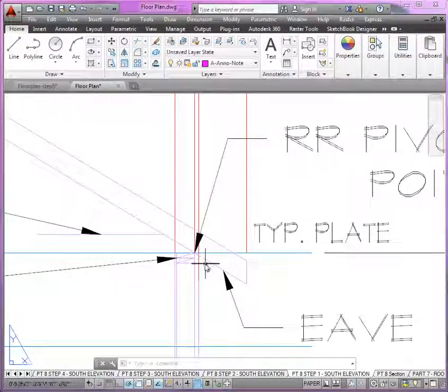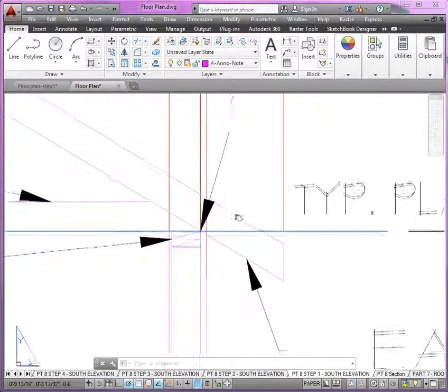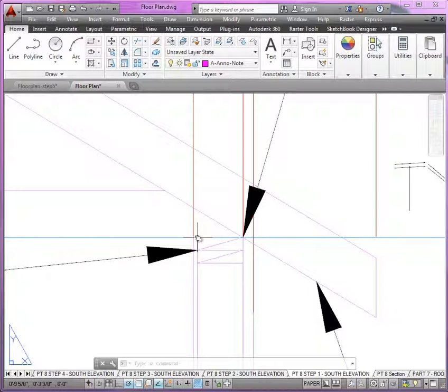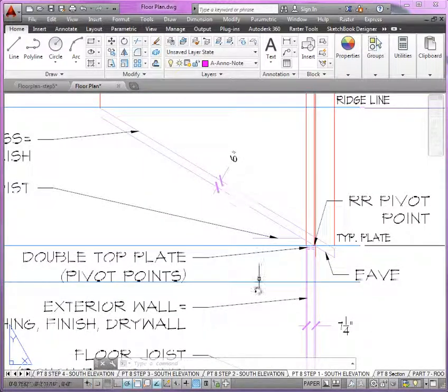This represents the bottom of my 6-inch rafter. You can see how it's aligned right here at the double top plate, on the outside edge. Now remember, we're doing it this way because this is a truss system. This is pre-engineered. If we were building rafters or our roof from rafters from scratch on site, most likely we would be using this inside line as reference. So you could see based on the dimensions of the lumber members now,